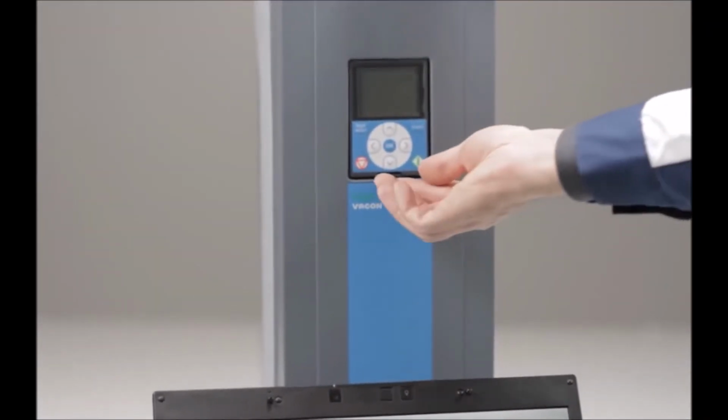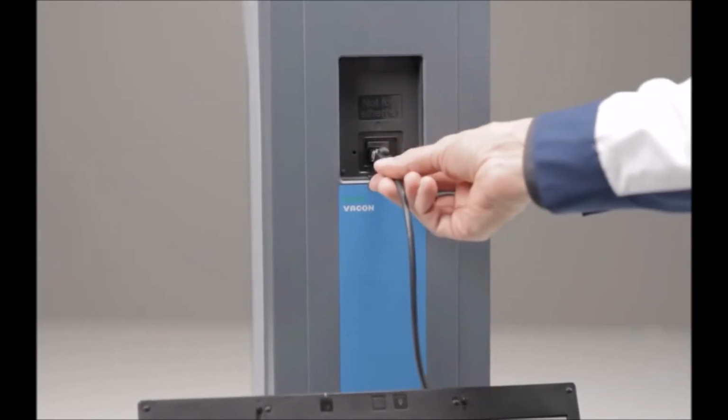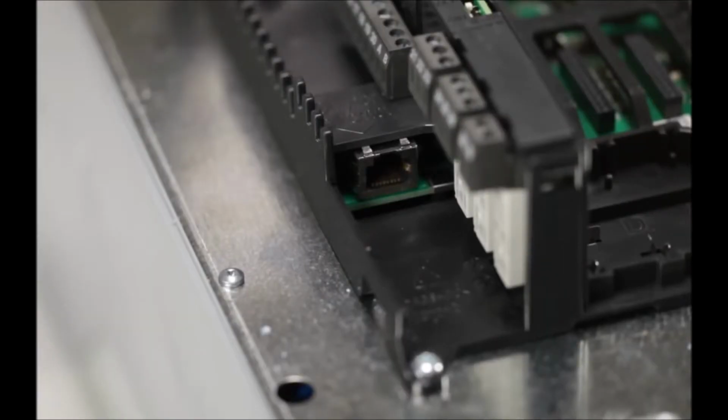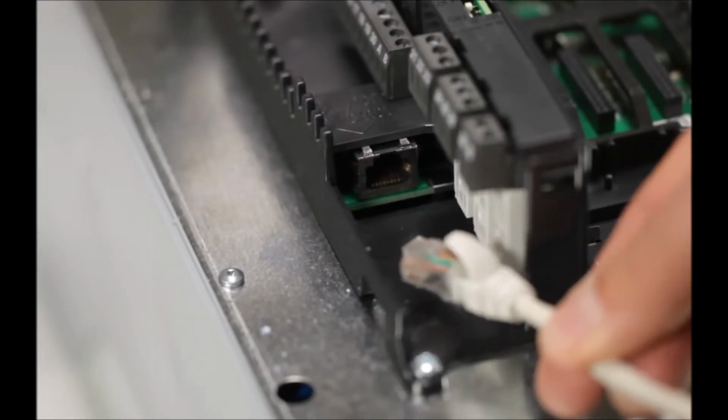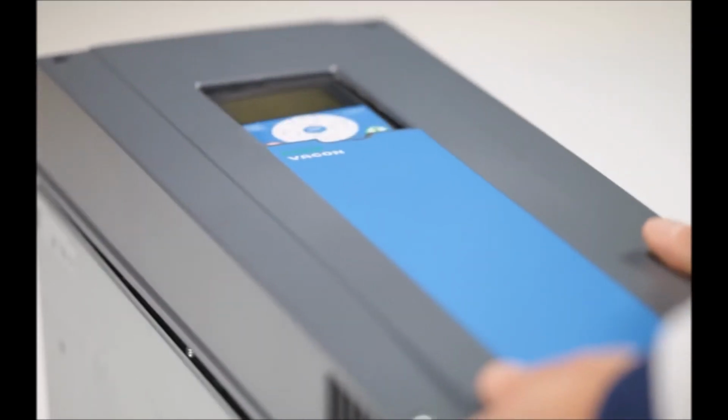First things first, let's show you how you connect your AC drive to a PC. It can be linked up either with a USB cable or using Ethernet connection. Both are done pretty much the same way, and VACON 100 Flow has ports for both. While both work in a similar manner, the Ethernet connection will be quicker.